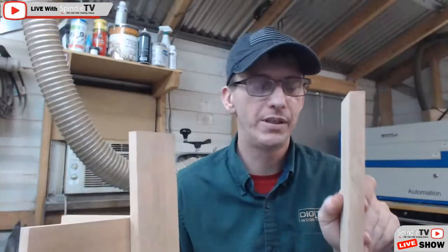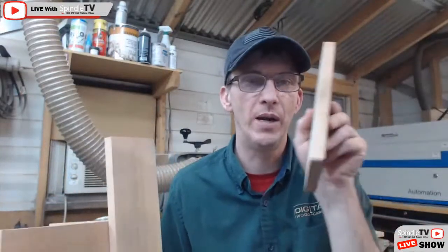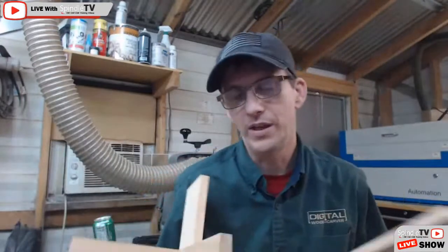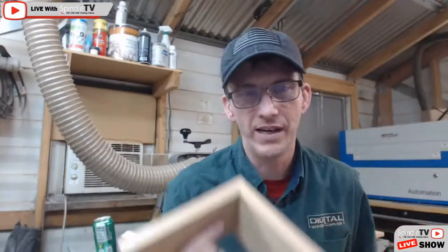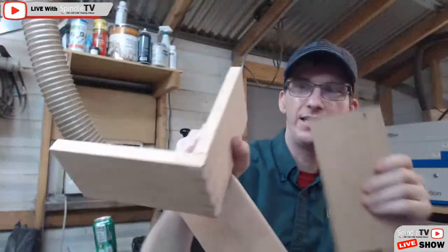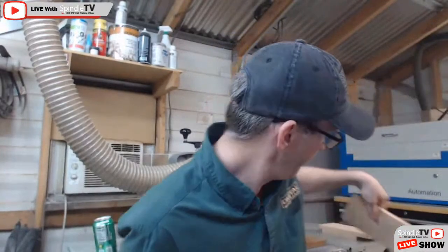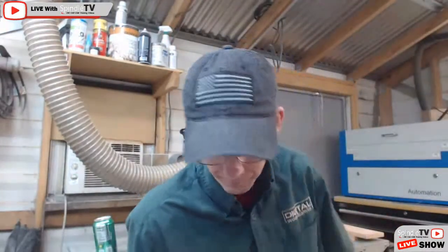On the pin boards, they're all pocket cuts, so I would just run them one at a time. So that's what I'm going to do. I've got my 1/4 inch end mill in there. I'm going to go back and cut the other 3 cuts for the tailboard, this one here. And then I will run my pin boards and everything.